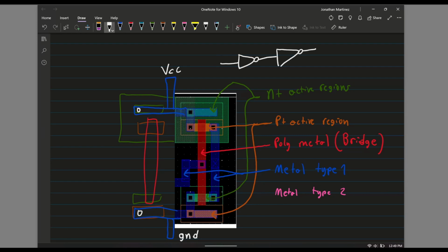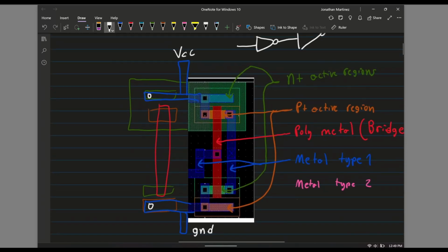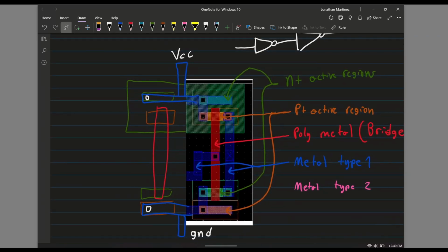Like that. Let's say I want to make something like that. So it's going to be very straightforward actually, and I've already started to draw out the first set of transistors. And what you'll notice is that I extended out this metal here towards the other side, and likewise with this side here. That allows me to share.